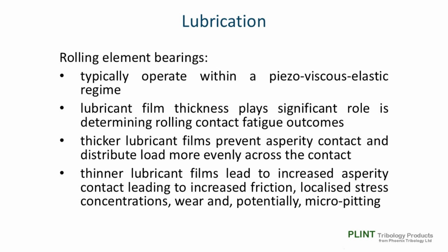So, under EHD, the solid elements of the bearing are separated by an extremely stiff glass-like film of lubricant. This prevents the surfaces coming into contact and wearing or micro-pitting, but obviously does not prevent the transmission of load across the contact, thus not preventing pressure-generated rolling contact fatigue and eventual macro-pitting failure. It is useful to note that the thickness of the elastohydrodynamic lubricant film is pretty insensitive to applied load, implying that the harder it is squeezed, the stiffer it gets.